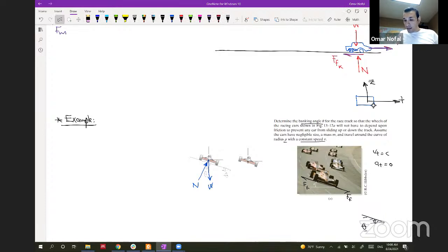And let's draw the kinetic diagram. This cross section will not show the tangential direction because it's outside of the plane, and we don't need it right now because the a tangential is equal to 0. So we only have the n and also z. And let's assume that the direction of the m a normal is in this way.